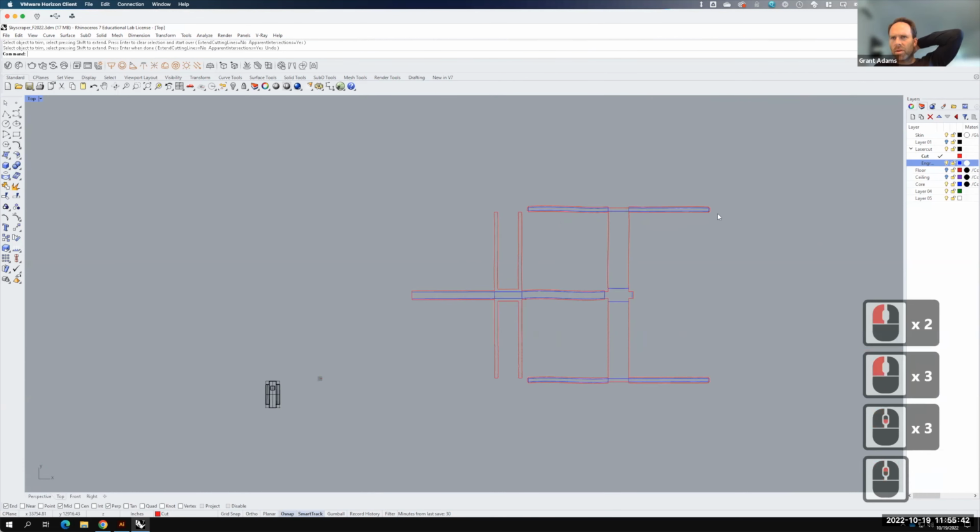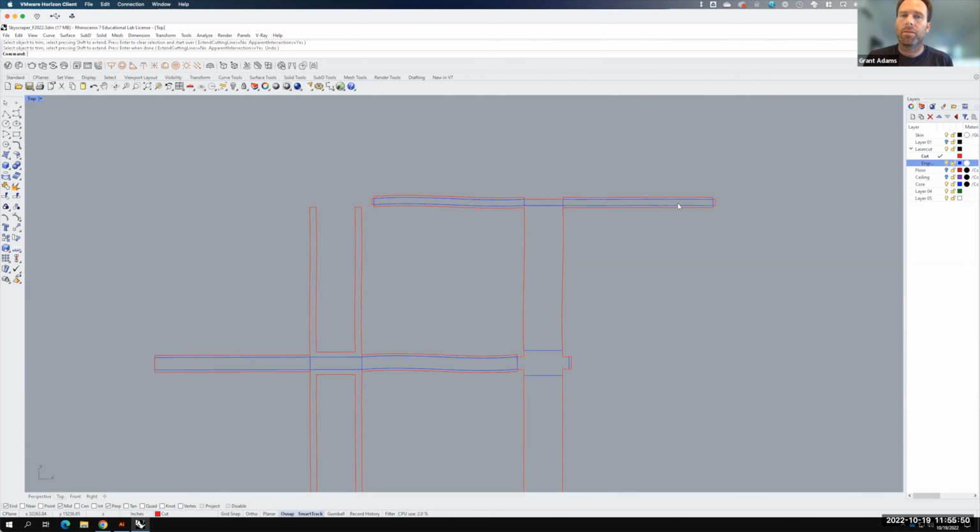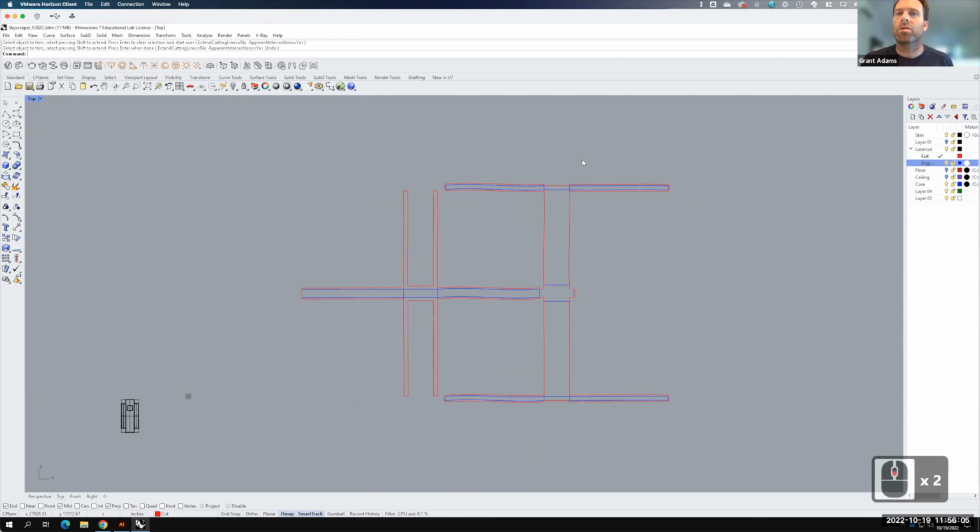All right, this is ready to be cut out. And if I were to cut it out and glue it together with those little tabs, the end model would become my building. And so it's a really powerful little strategy. What did that take me? A little bit less than 40 minutes to build this out. And now I could build a paper model of what my building massing looks like very easily. So it's a skill that's worth getting used to and getting to the unroll stage like this.